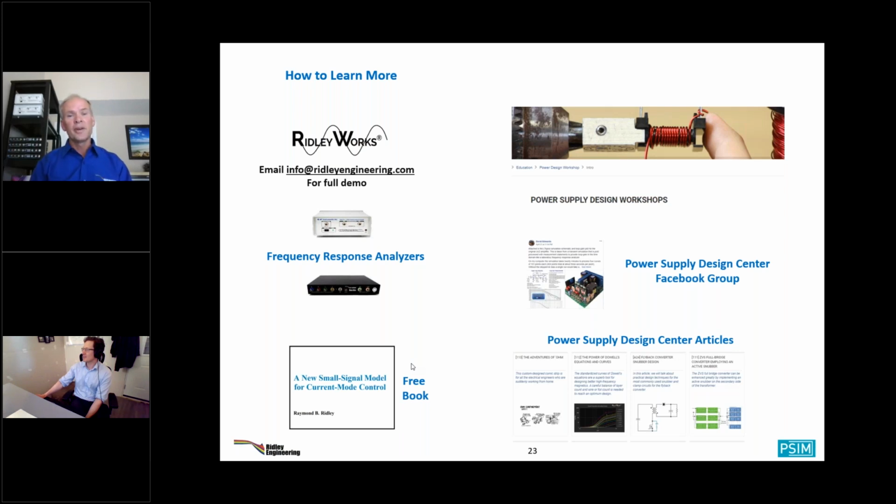And that's always true. Of course, if you're doing LLCs, I don't think anybody yet has done the explicit small signal model. It is a numerical model. So there you go, that's where PSIM comes in. You can grab our AP300 model all set up, ready to go, just drop it onto your LLC converter, sweep the circuit. And we've got the threshold levels and the filtering all set up properly for you, ready to go on that.